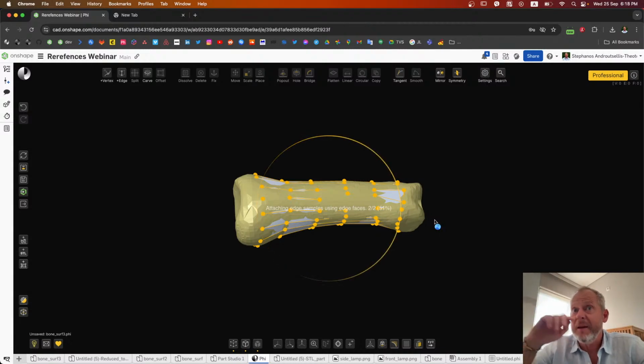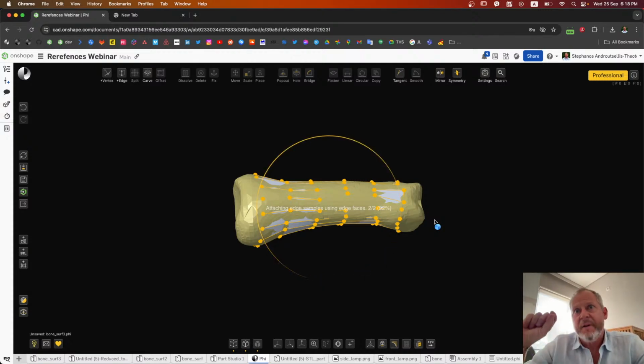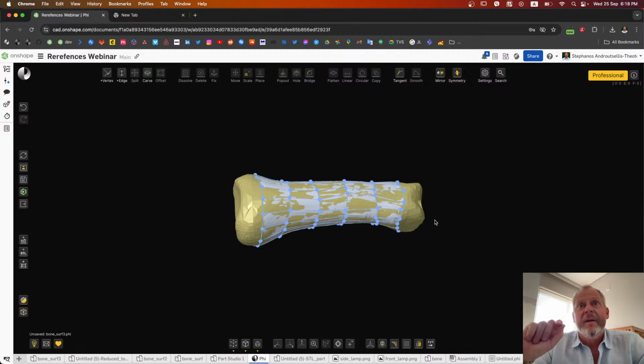And this is not, again, very simple, because we don't want to miss features. However, if we go exactly onto every little detail, every bit of noise, every little hole, then the surfaces that are defined by these edges will be a little messed up. They will be very, very weird. So instead, we found a middle ground where we try to follow the features of our model, but not really exactly where each facet of the scanned STL model is.